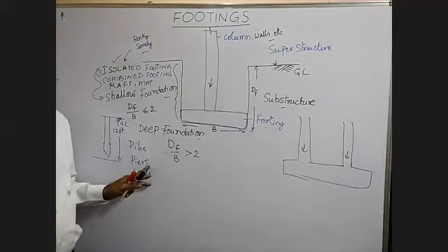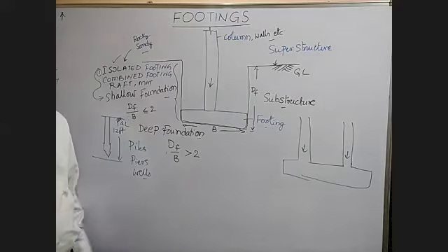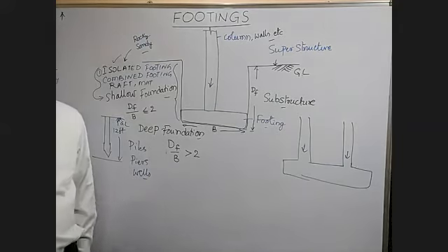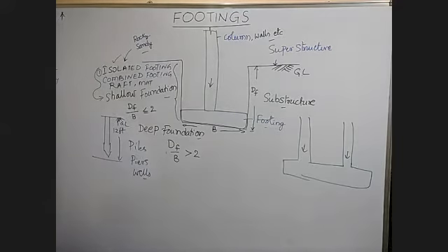For bridges and so on, they call them piers. They construct big size columns. They may be square or rectangular, whatever the shape may be. We call these piers, and of course wells are also used. So this is regarding the different types of foundations, shallow foundation and deep foundations. Okay, now the isolated footing is for a single column, and combined footing is for a group of columns.